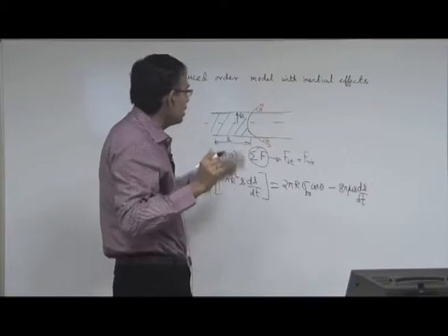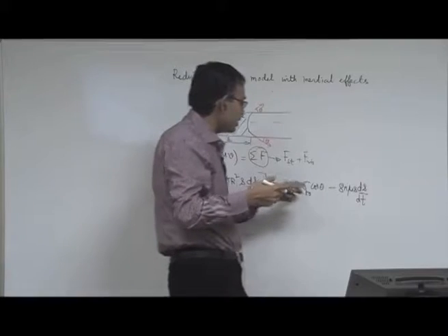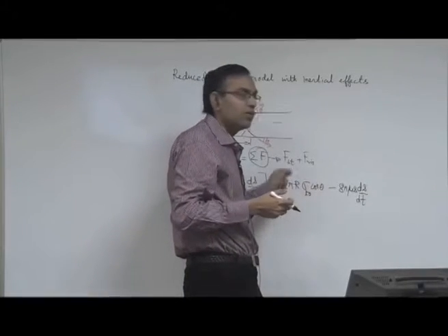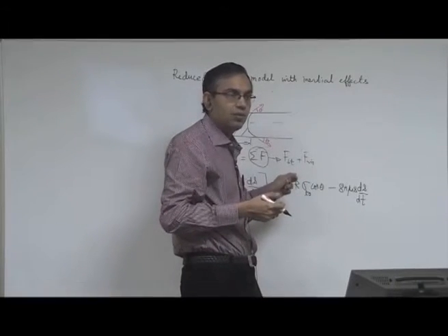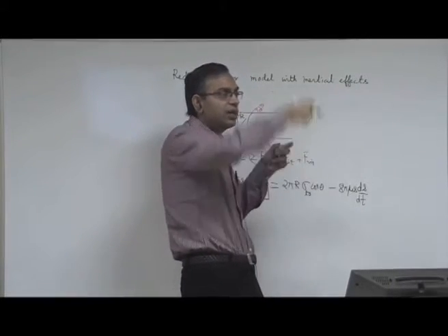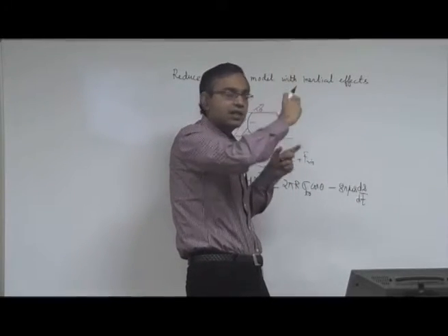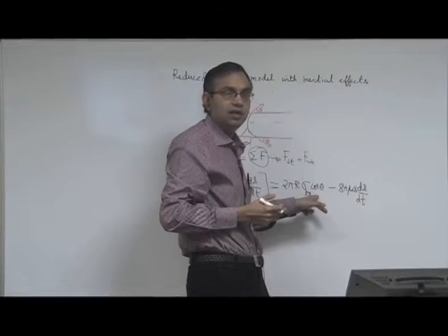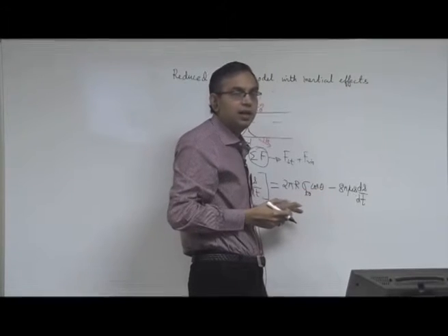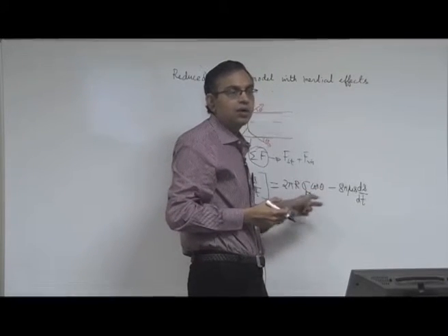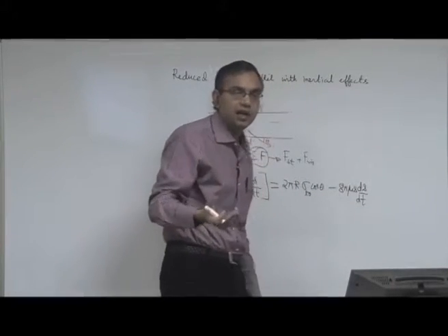That does not mean that in a horizontal or inclined situation an equivalent rho g or gravity effect is actually coming into the picture in all configurations. What it basically means is that if you dip it vertically, then whatever height it could have attained is the static height that could be expressed in terms of the contact angle. So, this is not at all a body force due to gravity, it can equivalently be expressed in terms of a static height, that is all.